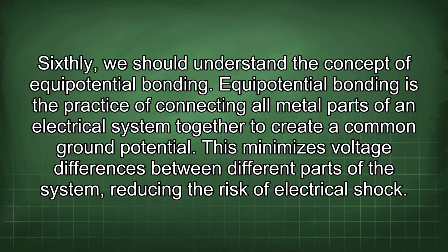Sixthly, we should understand the concept of equipotential bonding. Equipotential bonding is the practice of connecting all metal parts of an electrical system together to create a common ground potential. This minimizes voltage differences between different parts of the system, reducing the risk of electrical shock.